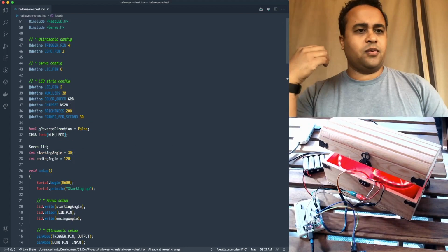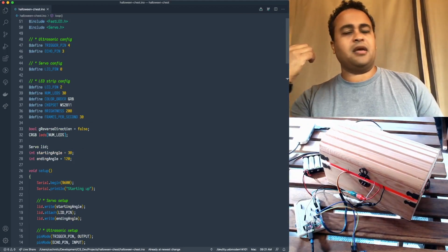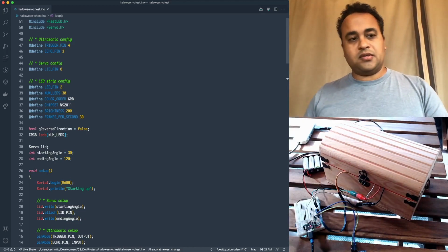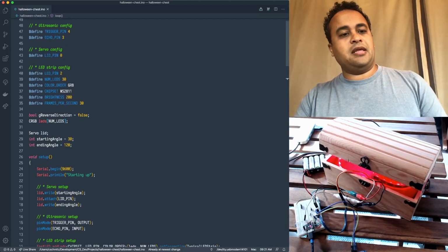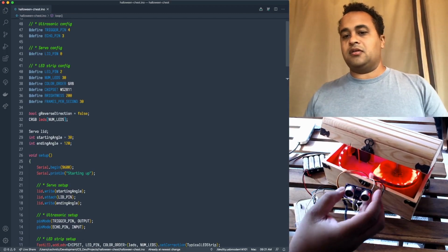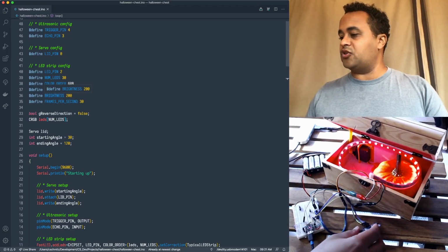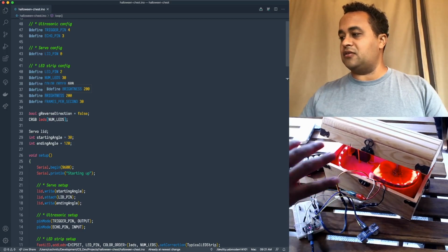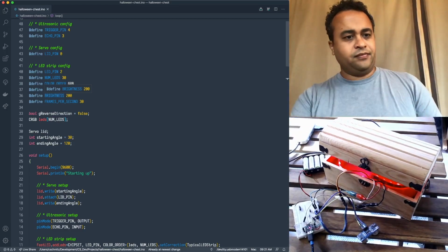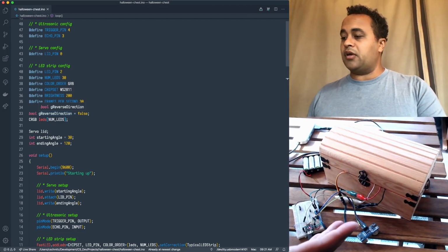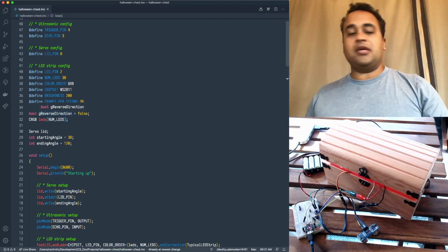So yesterday I went through and fit in the LEDs for the light pattern, the servo to open and close the lid, which is obviously in place, and then the ultrasonic sensor to detect the distance away from the treasure chest, which is eventually going to get fit into some part of this. And the problem, even though all of that is in there and working, is that we're running into blocking code.